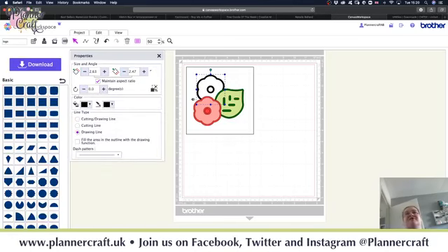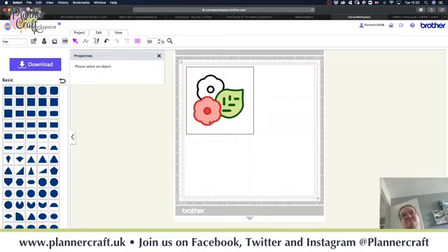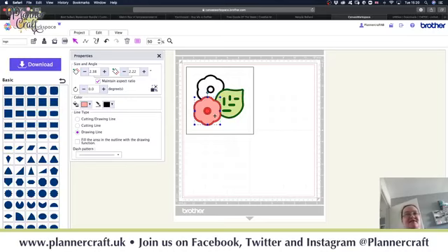We're going to turn our flower to a drawing line only, because we want that drawn on our card base. And because that will be the only element that we'll draw, because we're going to set other things to cut, we don't need to use layers. So everything else on here we're going to set to a cut line.